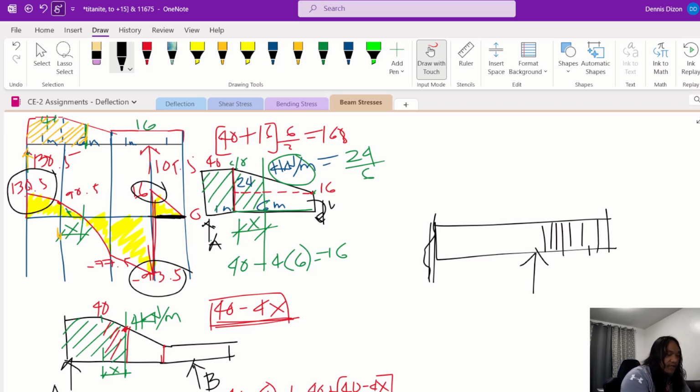But at the left of B, your shear is 93, so it is expected that the shear reinforcement at this location would be closer than in the cantilevered portion.